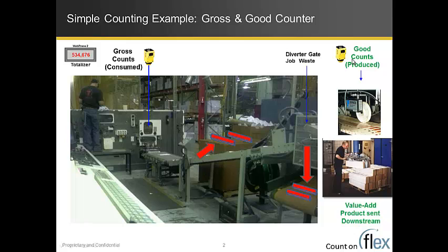And the other sensor that we like to get on certain machines, where it's possible to get a good count, such as a web press. So for example, if we have 1,000 units go through that machine, all the paper that came through the machine would come out at this location. 1,000 came through the machine, and we see that 800 good units actually came off the machine.